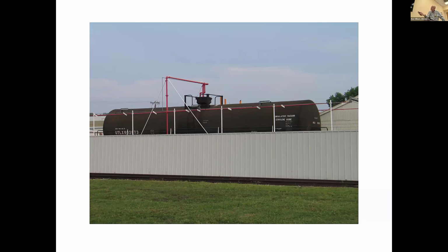Here's another tank car. This is ethylene oxide, and the difference here is that all that red piping is fire protection sprinkler piping. So if you had a fire out there, that sprinkler piping would control that fire, maybe put it out, but particularly control. So again, ask yourself, what kind of a product am I doing here? Loading, unloading. Could I add fire protection to the loading facility in case we have a fire situation, sprinkler systems around it and things like that? So that's the red piping.